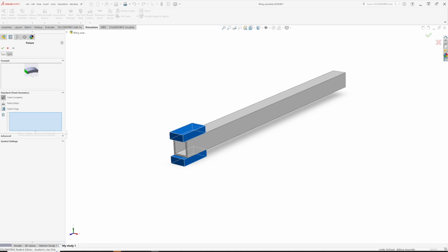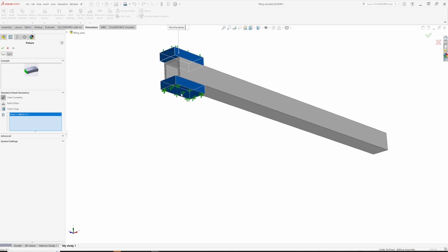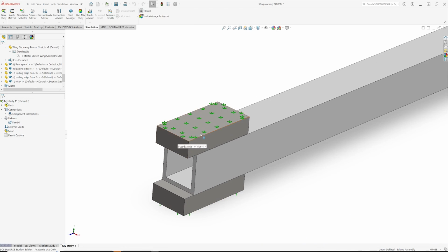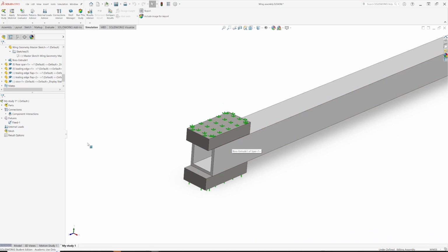And there's a nice little graphic here, showing that if we click a surface, that's the bit that's not going to move. So for the vice, we're going to select the top and bottom surfaces, assuming those bits can't move. Little green icons appear on there showing that these things are fixed. And so yeah, when we apply load to our beam, these things aren't going to move.